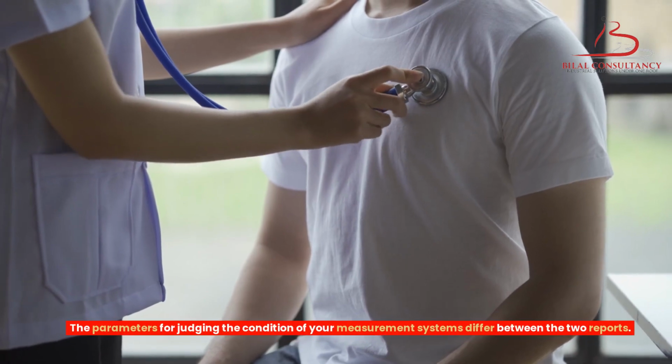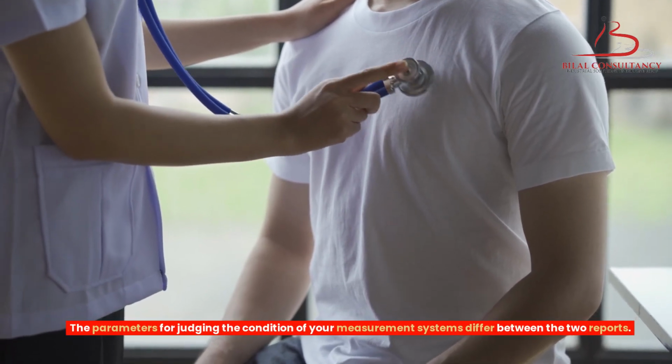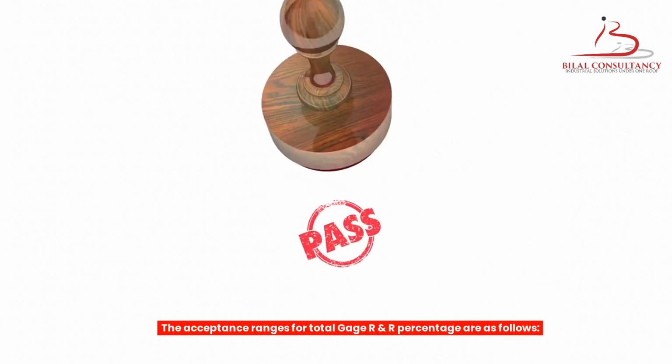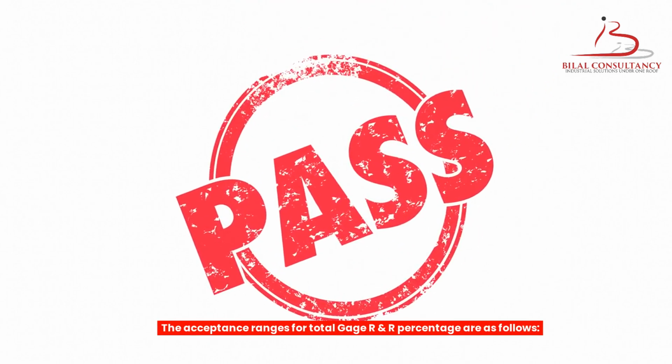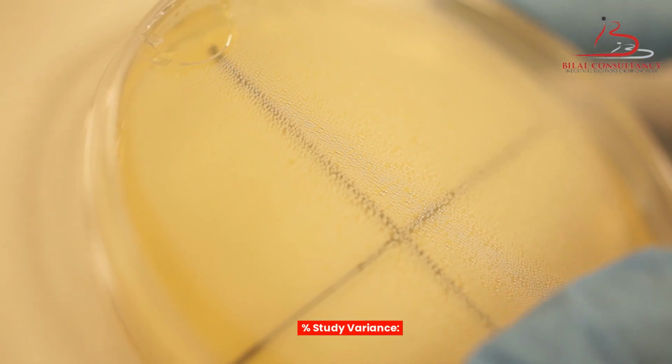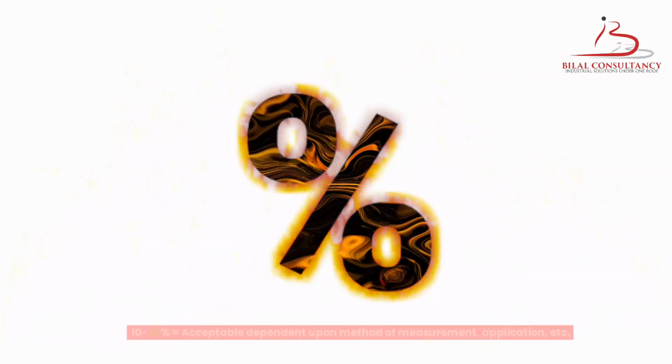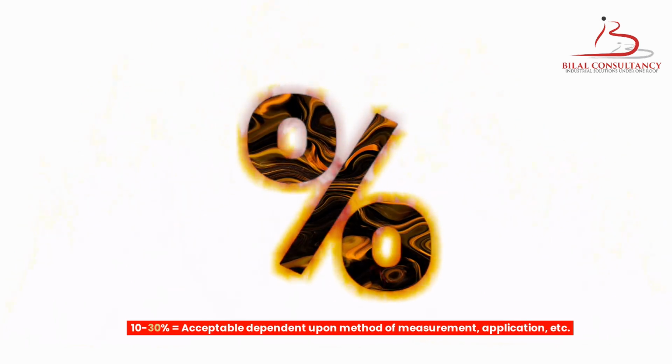The parameters for judging the condition of your measurement systems differ between the 2 reports. The acceptance ranges for total GageRnR percentage are as follows. Percent study variance. Less than 10% equals acceptable. 10-30% equals acceptable dependent upon method of measurement, application, etc.